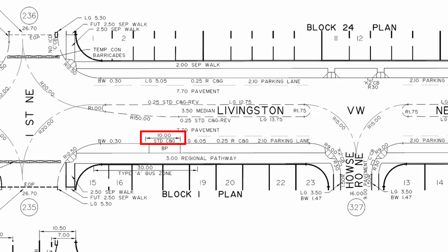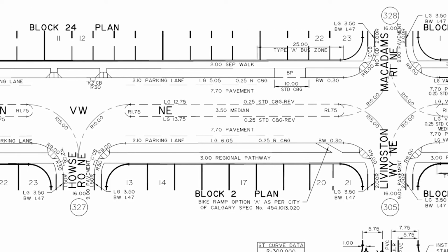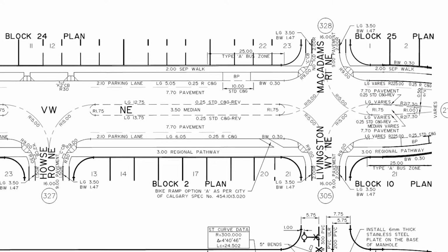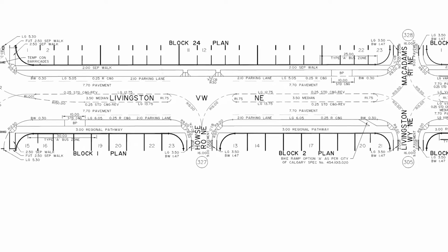This means that for the 10-meter section in front of the bus pad, there is standard curb, not rolled. In sections where the lip of gutter and property line are not parallel, the plans will state "LG varies along the lip of gutter." Like we said earlier, the goal of being able to read a plan isn't just to read for pleasure. The plans are a tool to help you build the road. How do you actually use this information?